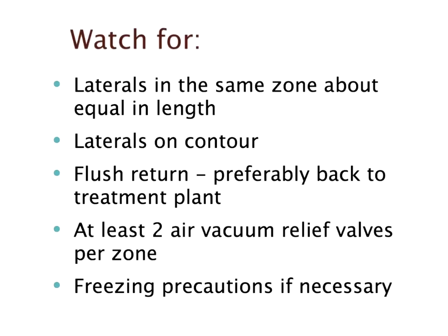Generally, on small systems, you can do this. Every now and then you come into a very large system where you cannot hold the contour. In that case, Geoflow offers one specific dripper, which I'll talk to when we get to that point. But we don't recommend it. Hold contour if at all possible. It's the safest way to go. And when I say hold contour, I don't mean with a laser, but within 6 inches or so as you go along. You don't want to be too far off.